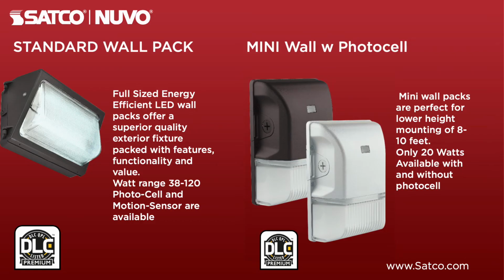Our standard wall pack is full-size, energy-efficient, LED, and offers superior quality packed with features and functionality and value. Its wattage range from 38 to 120 watts allows it to be mounted up to 20 feet high. Available are photocell and motion sensors. For lower mounting heights, 8 to 10 feet, our mini wall packs are perfect. These are only 20 watts and also available with and without photocells.